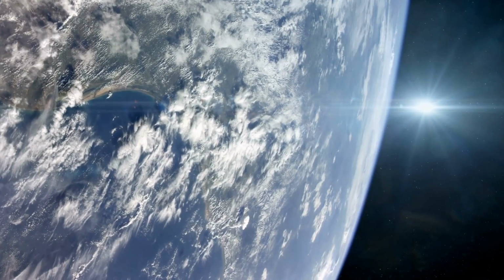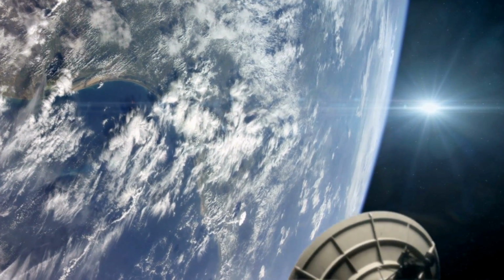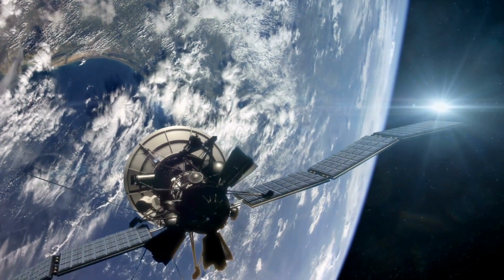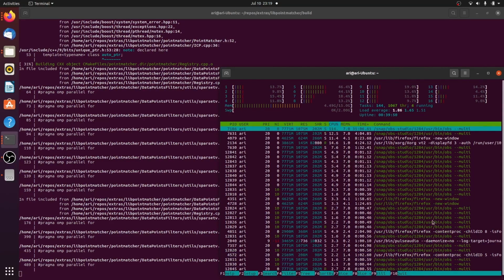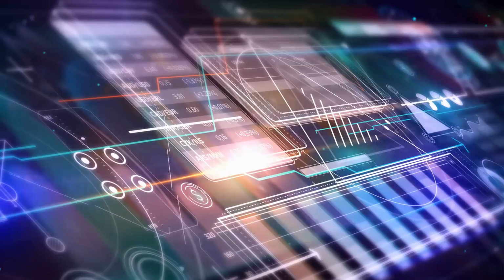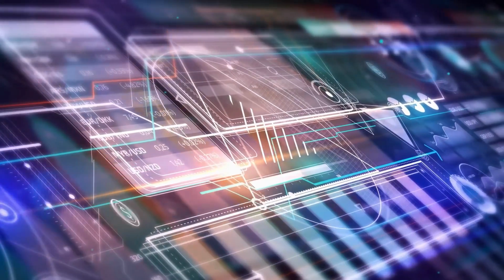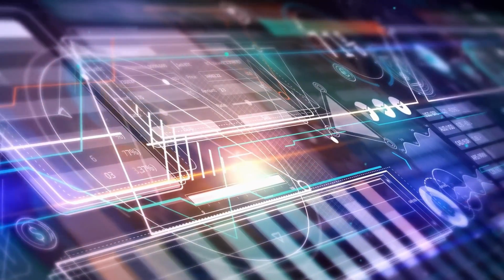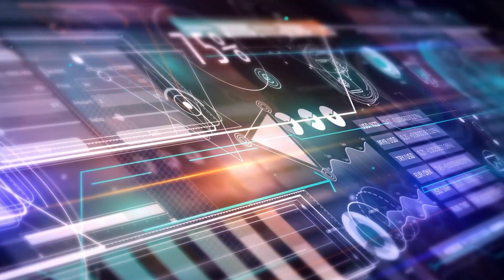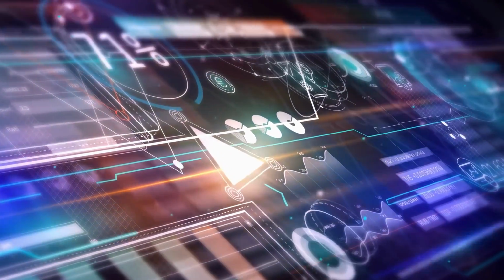That person needs to basically have the high level overview of what each of the different systems are, and how they run. They need to be really good at multi-threading, really good at understanding how the operating system runs, understanding how to manage the CPU load and the GPU load, and making sure we don't go overboard on that. So understanding full system diagnostics, I guess. And with that, it can be really useful to export that diagnostic information so that you can see plots over time to see if something happened over a period of time. Was it just the system that had too high of a CPU load that was reacting in a weird way so that it ended up having these weird functions?